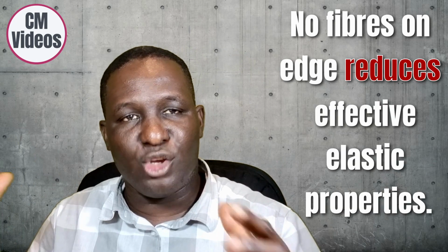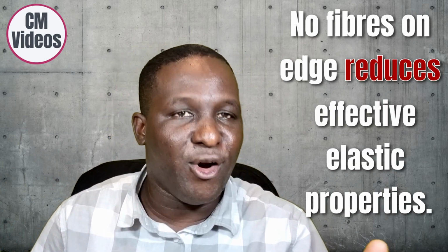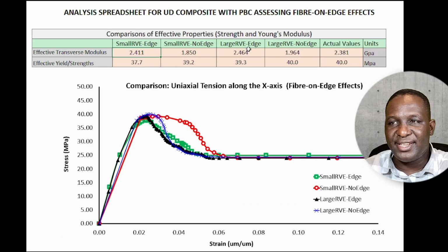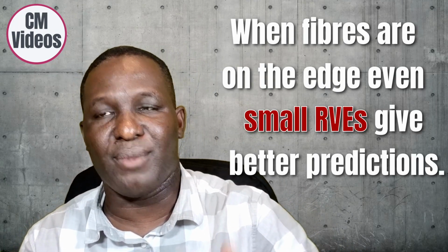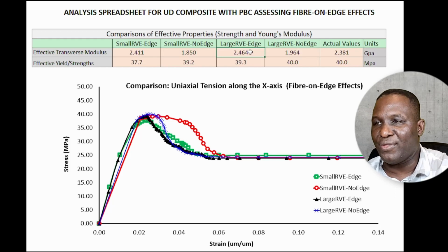And so what we can first see right away is that if you don't have fibers on the edge, your effective elastic properties, the Young's modulus of your composite, will not be correct. It will be way off from what you will expect when you have fibers on the edge. When you have fibers on the edge, they are quite okay. So there is really not a lot of difference, 2.411 and 2.464. Even for a small RVE, you're getting a good prediction compared to what is recommended in literature, which is a larger RVE, precisely because it's got fibers on the edge.